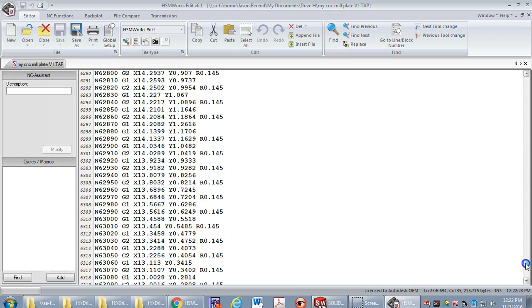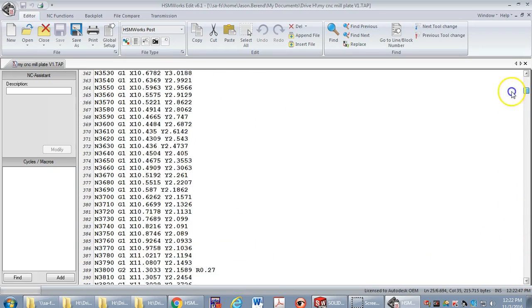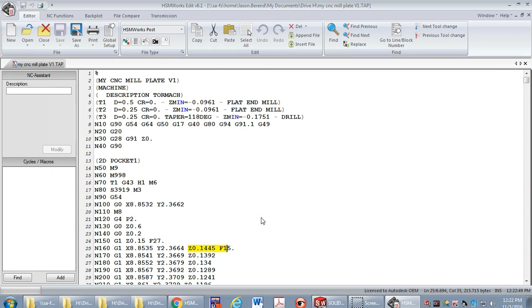There's tons of lines of code, but the machine can read these codes very fast. So our code right here is 66,830 lines of G code. So you put this on a flash drive and head over and get help from myself or an aide. And we will always do a dry run. So we will set the Z 1 inch above your work, and you will watch this whole thing go in midair before we actually dive into the metal.